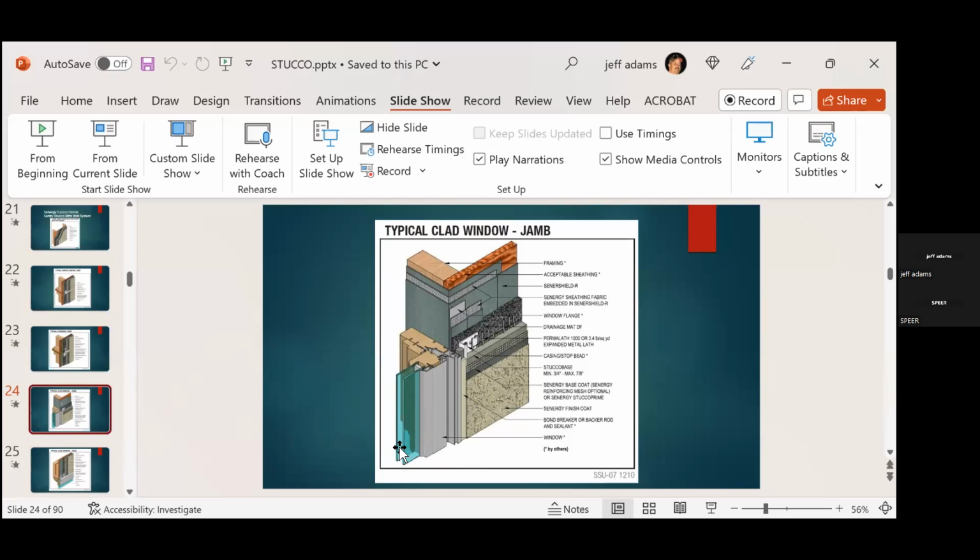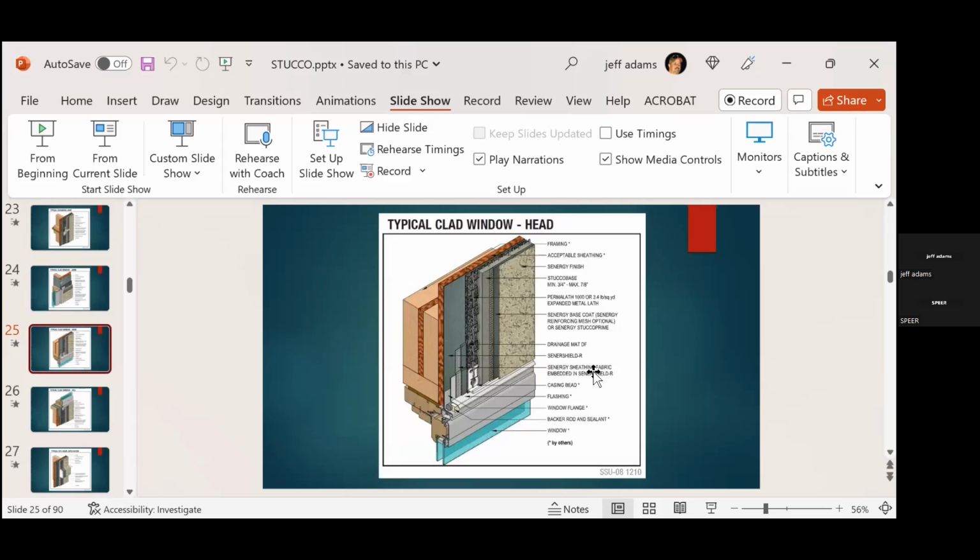And it would continue our expansion joints up, because our expansion joints would switch over and go from here. And that would continue up the wall section with that. Let's see here. This is getting into your weep screed with a flashing detail that kicks it down.